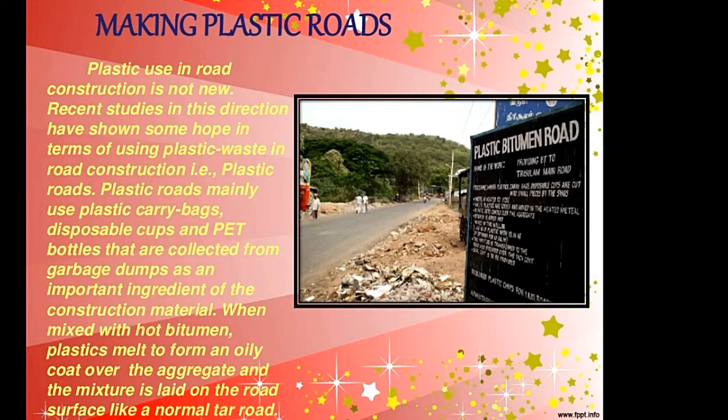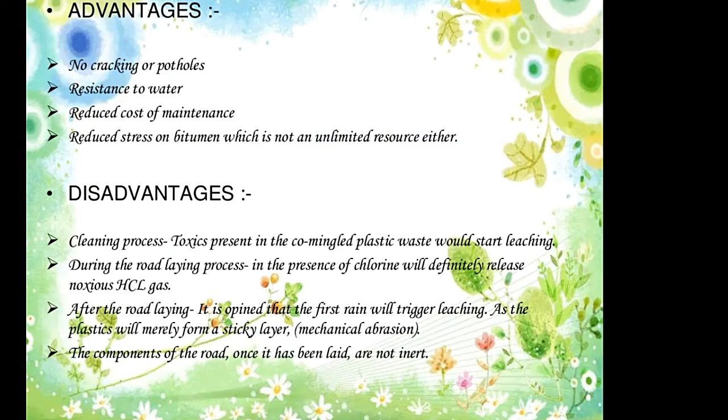So that's a good idea. Plastic anyway is pliable and can be bent and will not cause the road to crack. And I guess that's the future of road construction. Advantages of this plastic thing: no cracking or potholes. That's what I've said a while ago. Resistance to water, reduced cost of maintenance, reduced stress on bitumen, which is not an unlimited resource either.